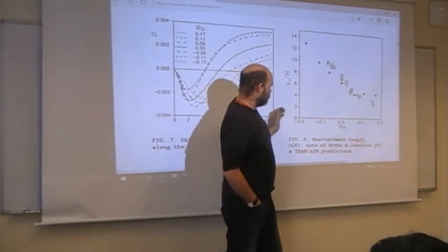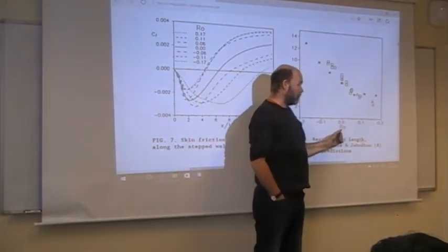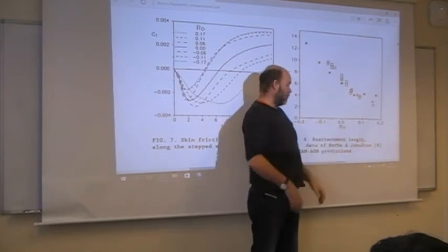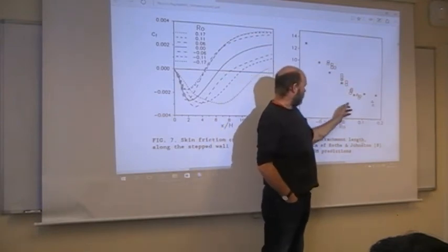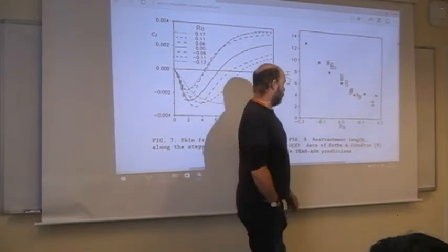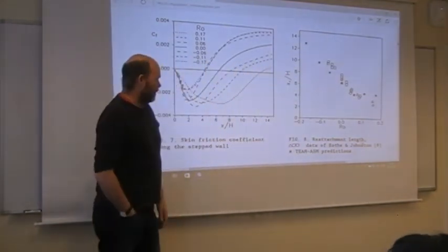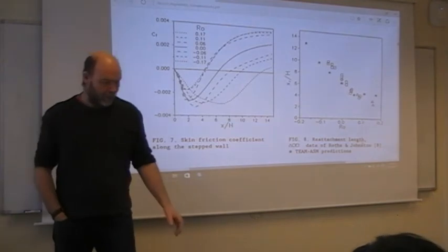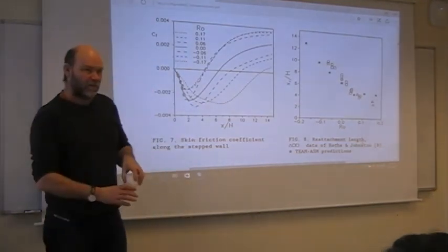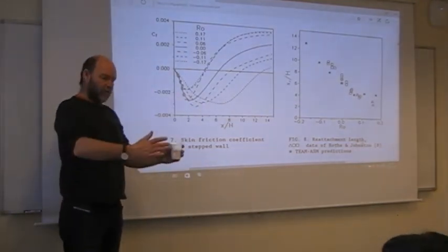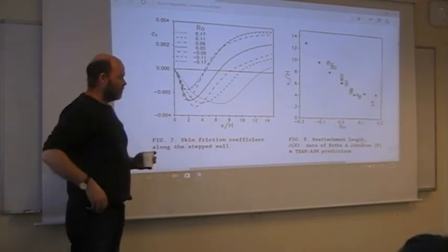With positive rotation, increasing the turbulent activity, you will mix it up faster, so you will have a shorter and shorter reattachment length. There isn't that much experimental data with rotating channels. It's not that easy. You have to take the entire channel on a turntable, so it's a little bit messy.